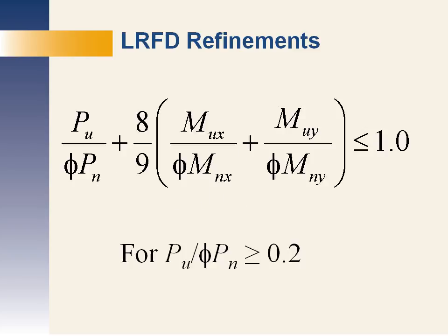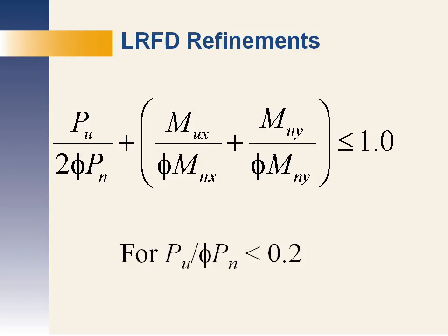Second-order effects were included in the calculation of axial forces and moments. This greatly simplified the resulting interaction equations. And what's shown here is the LRFD interaction equation for high axial force ratios. And this one shows the equation for low axial force ratios.